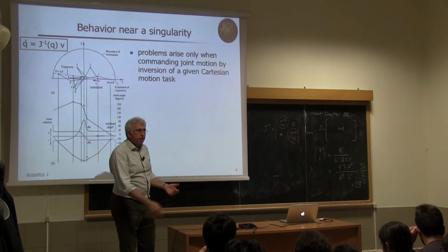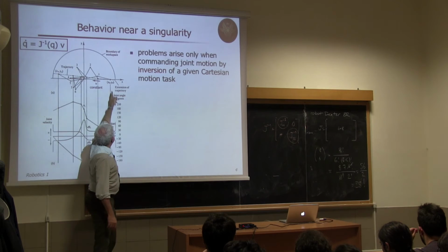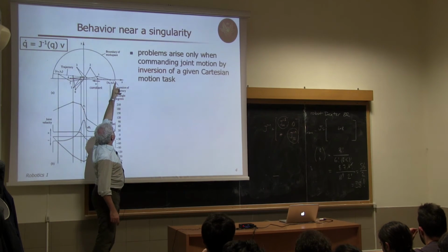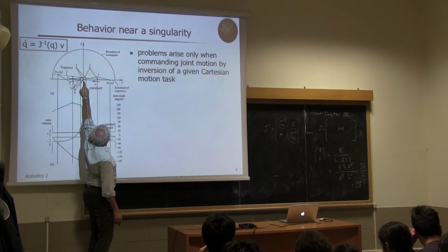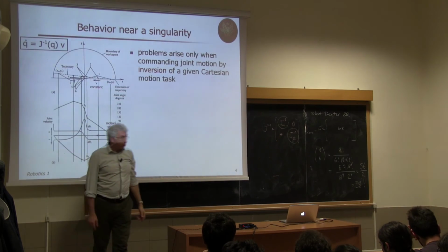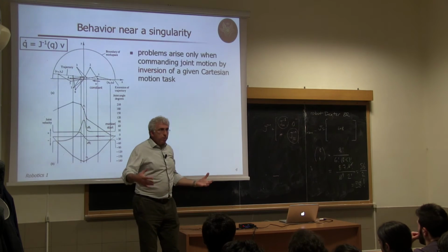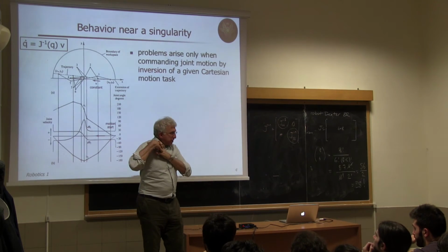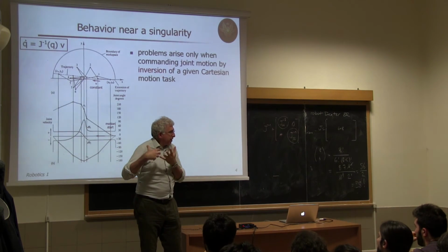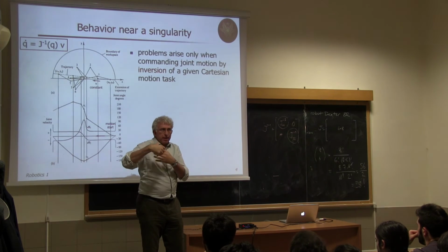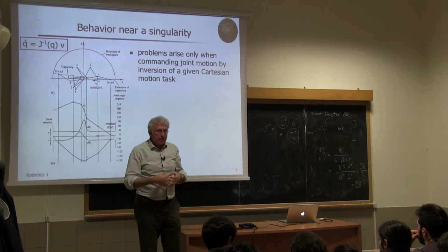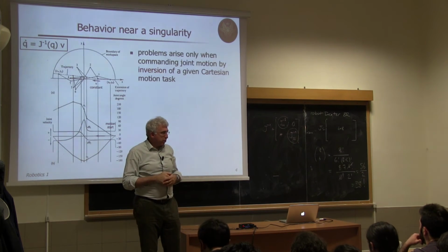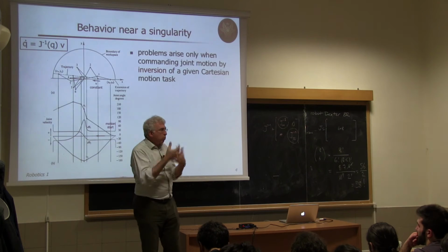You go there. However, you can see that we start relatively close to the boundary, but not so much. And this path comes close to the origin of the Cartesian space. And we know that the origin of the Cartesian space is associated to a singularity. In fact, in this case, we would have an infinite number of solutions if we were exactly passing through the origin, because any value of Q1 would work.